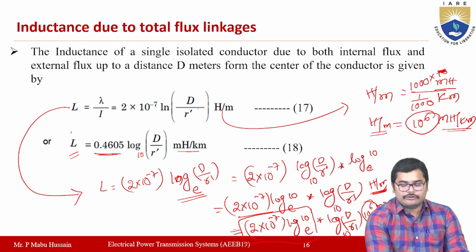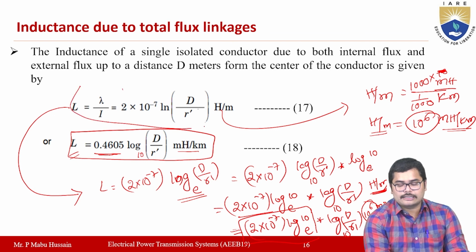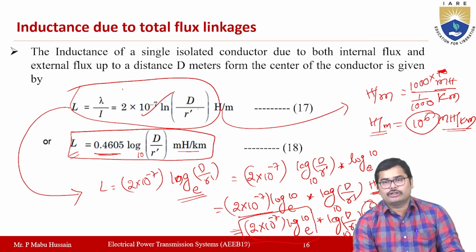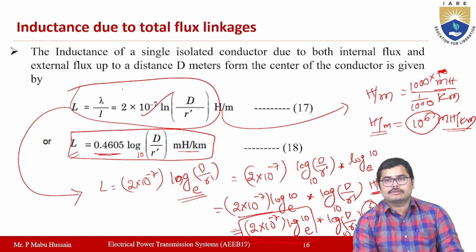You can remember either this equation or this equation also. This equation is easy to remember, 2 into 10^-7 ln d by r dash. Remember this expression so that we can solve some numerical problems later.